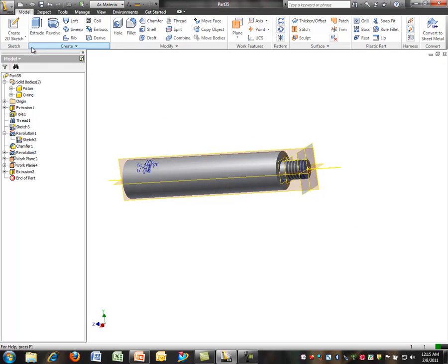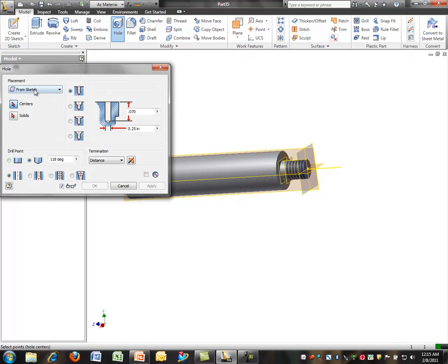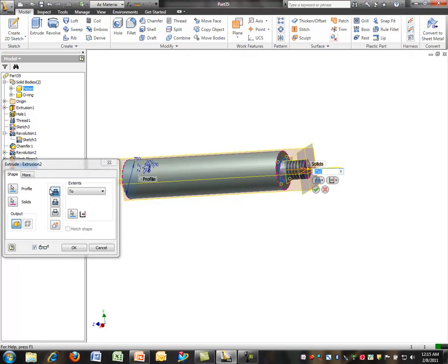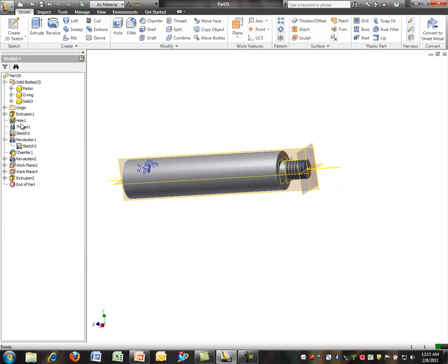And now let's create a hole in the body. Actually, one thing we want to make sure of, if you notice, when I created the extrude, I left this button pushed. Shame on me. That's going to fuse the body and the piston together as one solid. I don't want that. I want to create new solid. So I'll do that, and notice I get a new solid up here. Let's go ahead and rename it as the body.